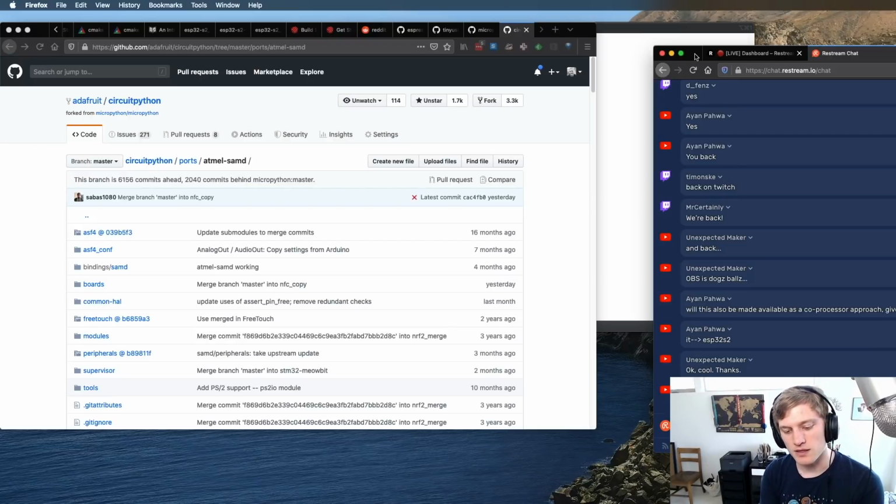And then the other thing that informs that is thinking about lifetime. So the display IO work was a huge amount of work because I wanted the display to last longer than the user's Python code so that we could show errors and stuff on the screen. And there's this thing in MicroPython called the web REPL, where you can go to a web page and do a socket and get your serial input and output. And I don't think I want to do that. That will add complexity because it has that same problem of its lifetime being different than the user's code.